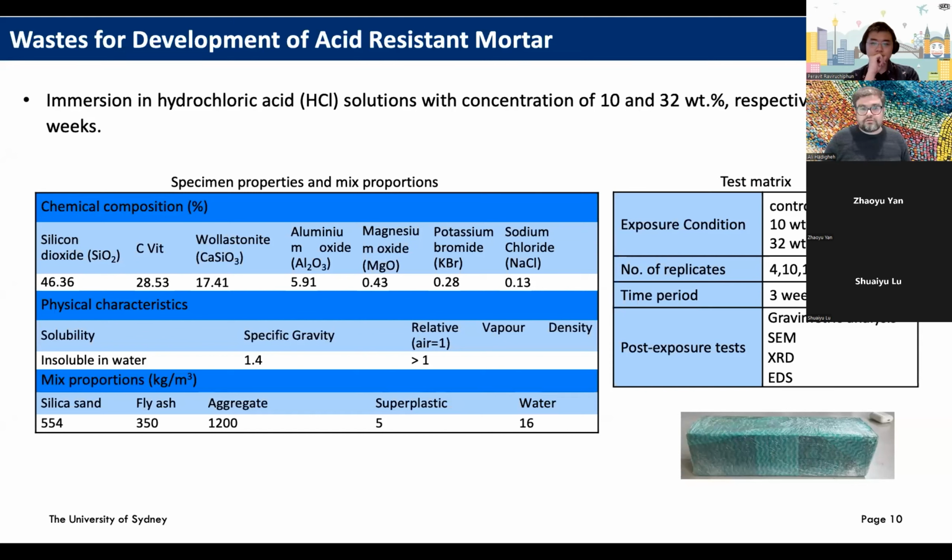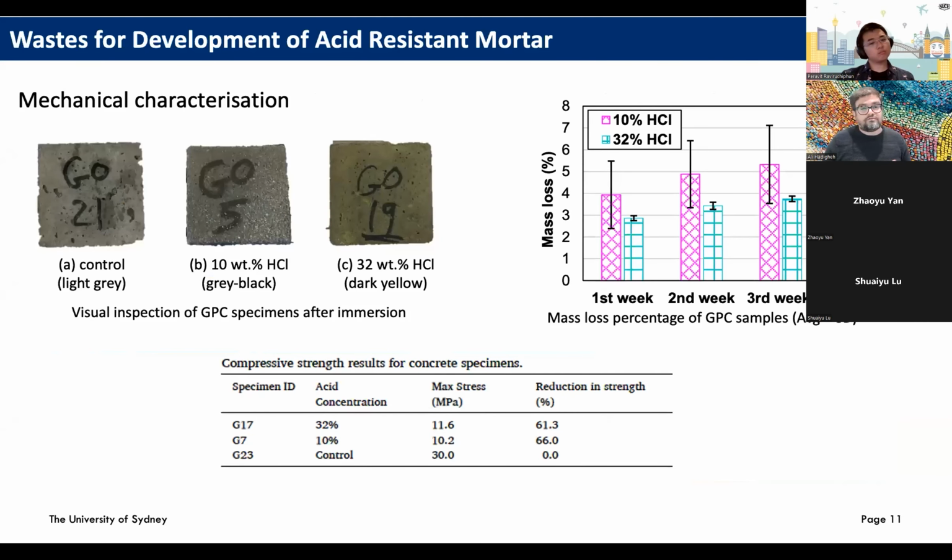So that's why we tested HCl on these concrete samples. We tested them during the time we cast them, and then we looked at properties of these samples in terms of mechanical properties, such as compressive strength test, tensile strength, shear, slant shear test. So you can see a couple of these results, for example, mass loss of samples within these acids.